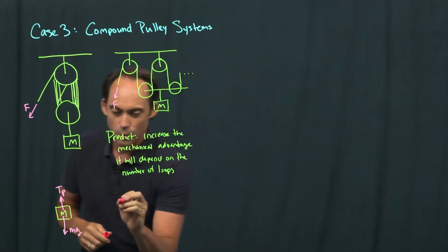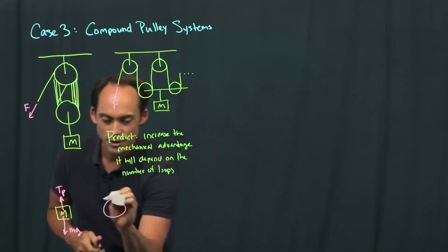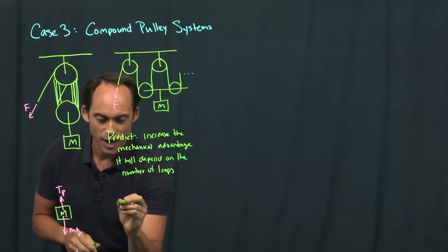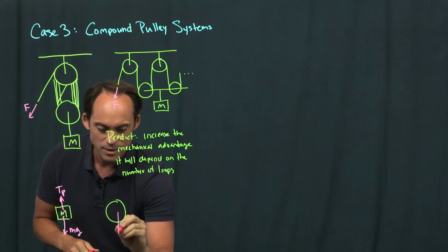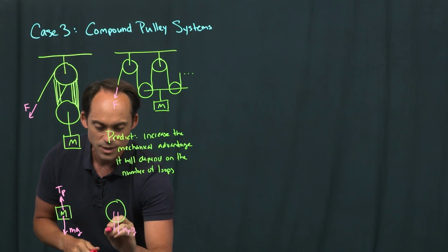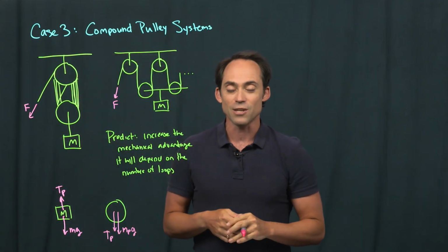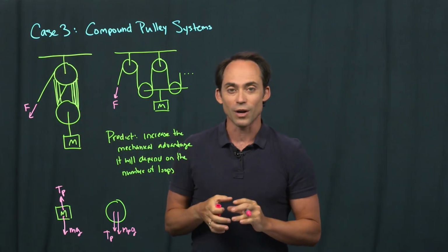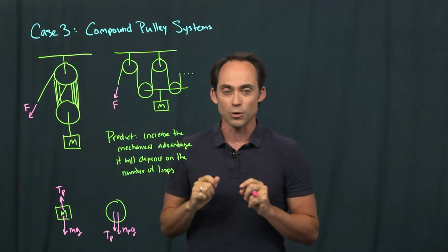And then for the pulley wheel, we've got our pulley and we've got its weight, which I haven't specified but might be present. We've got that tension force that's connected to the mass, and then we've got a whole series of tensions that are applying for every string that's wrapped around here. And in fact, there's 2 for every one, because we've got a string that comes in and comes out. Both sides are pulling the pulley wheel up.